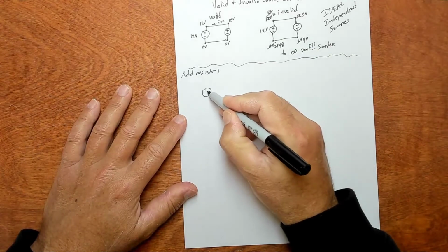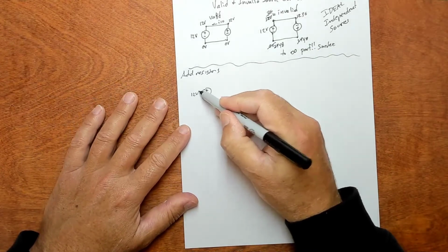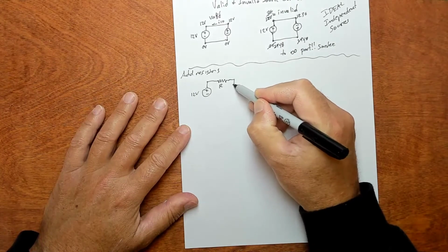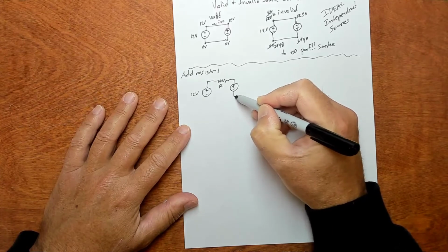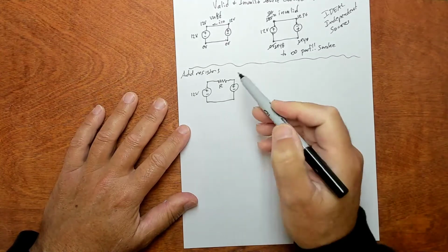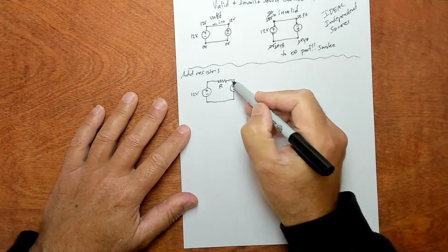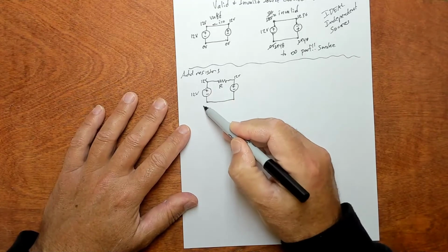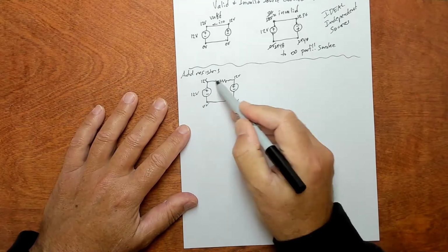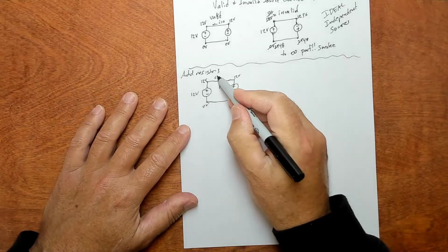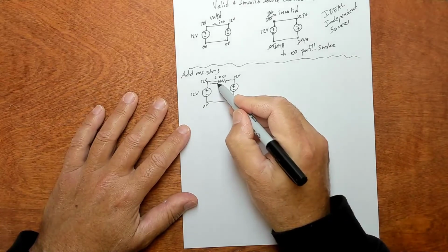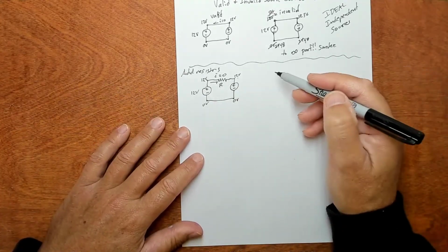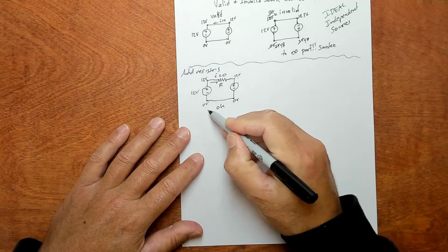So let's say you had this thing, 12 volts, and then you stick a resistor in here, R. So this is the so-called valid connection, the plus to plus and minus to minus, but I've added a resistor. So still there's no voltage potential. There's still 12 volts here and 12 volts here, and 0 volts here and 0 volts here. So there's no potential difference across the resistor, so I equals 0. You can put an arrow for the I direction, but there is no I. Because there's no potential difference, so there's no current I. So this is still okay.